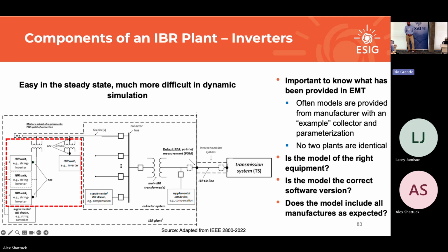But that also looks a lot like an aggregated real plant model, right? So it's really important, and this is an EMT specific nuance, to ask: did I get a plant model, or did I get one of the example models? This sounds really simple, but it's something that gets missed a lot of the time.